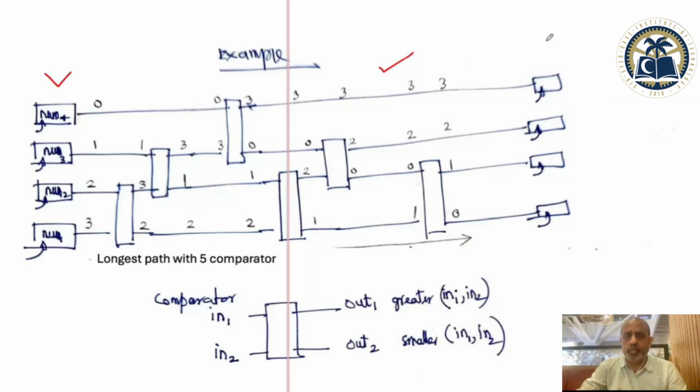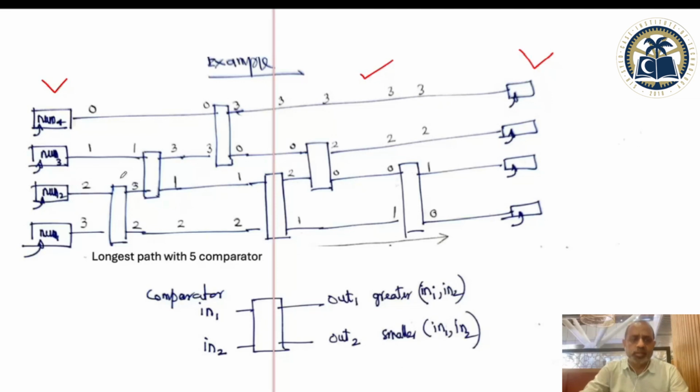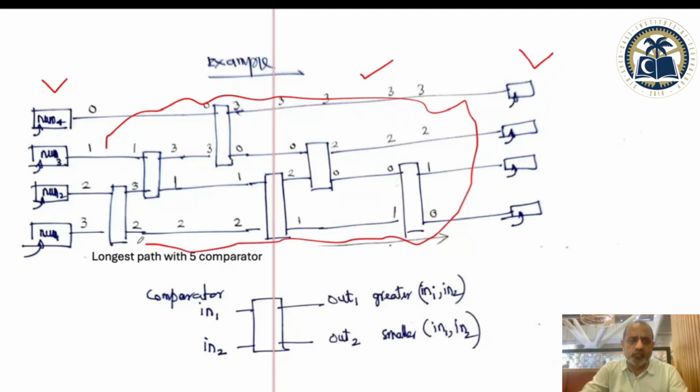So we don't have any register in between, and we said just this whole combinational cloud, which is consisting of many comparators. For the four inputs, you can count the number of comparators: one, two, three, four, five. So five comparators. And you can actually come up with a formula. It's always going to be like this. If it is five, so it is four, three, two, one.